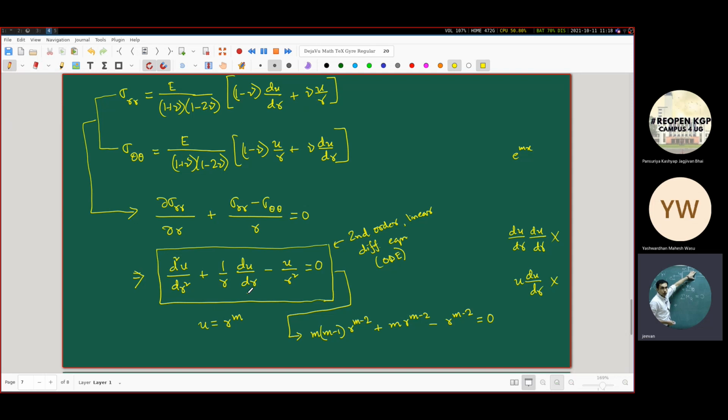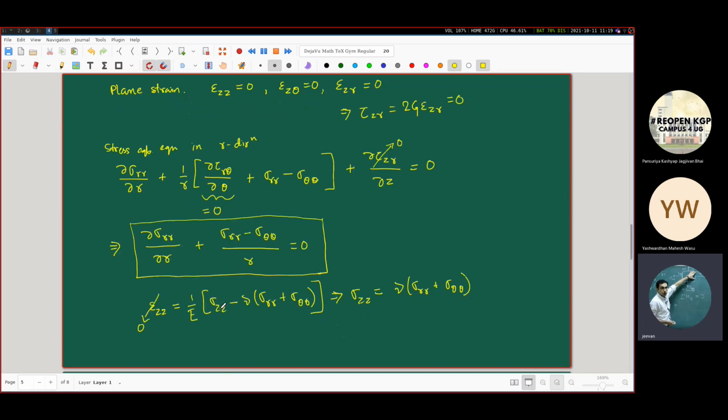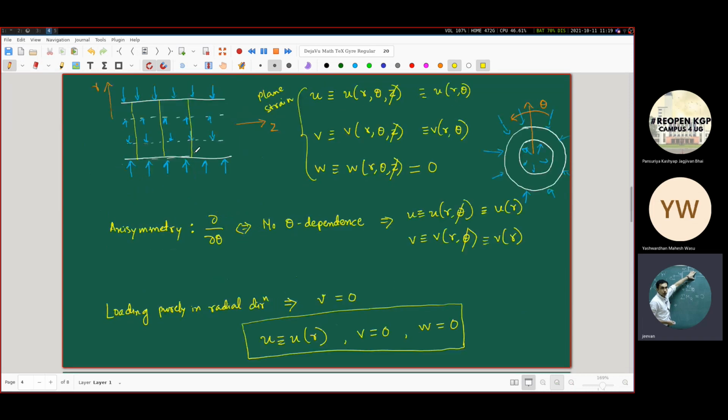This is not just some arbitrary mathematical problem. So we have to connect this somehow to the physical condition. Now, ideally, we would have wanted two conditions in terms of this displacement variable u directly, but we don't have that, because if you go back to the diagram of the pressure vessel, you have nothing directly in terms of the displacement here. Through our ideas of elasticity, we have obtained a governing differential equation in u, but nothing in this physical problem is directly in the form of the displacements. So what can you do?